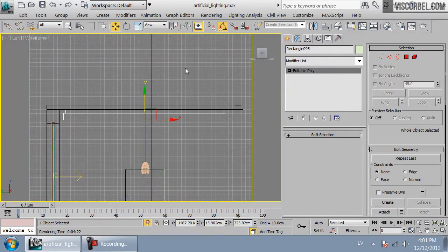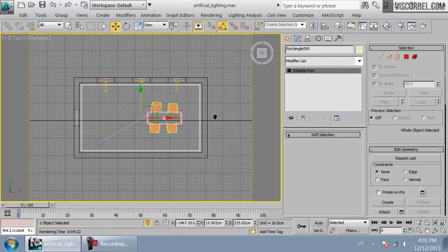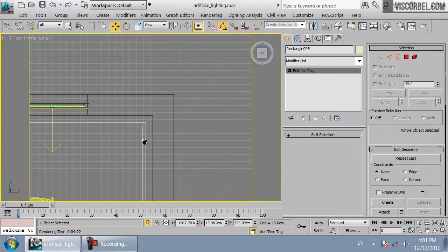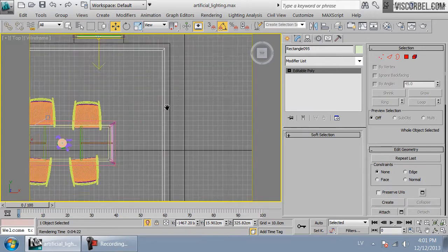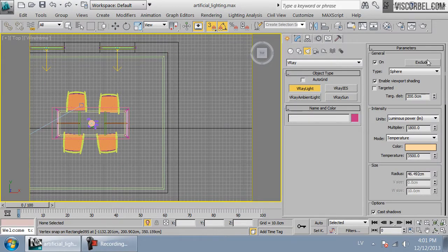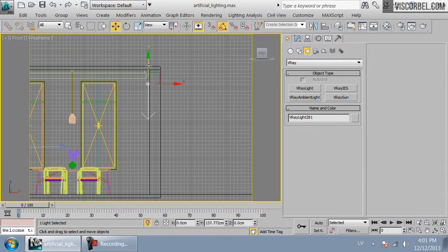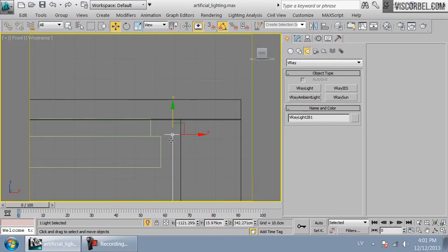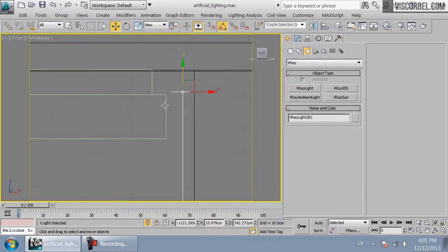Many people that have not seen these lights in real life, or do not know how they are constructed in real life, usually use a technique like this, where they create a plain light, point it directly downwards, and expect it to look good. That's really not how it works. You do not put the lights in this direction, since if you can see them in render, it looks weird: they are too bright, or too aliased, or the light distribution looks weird.